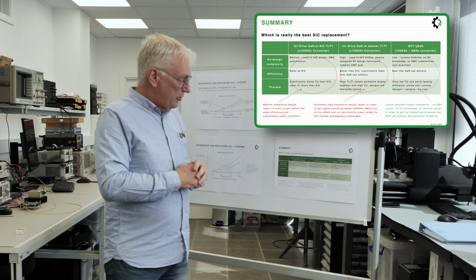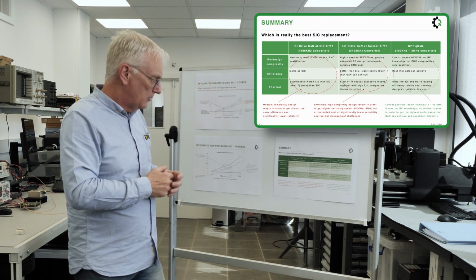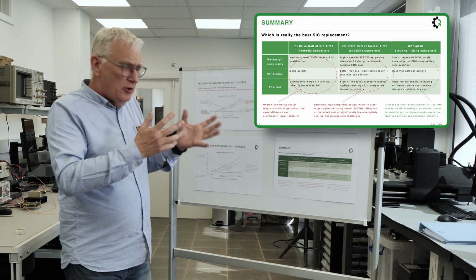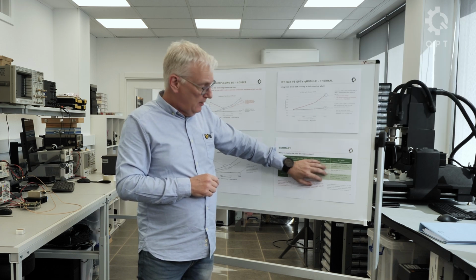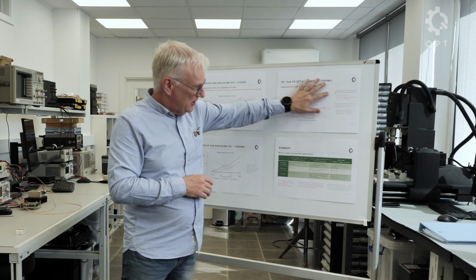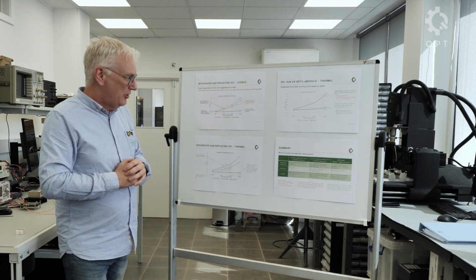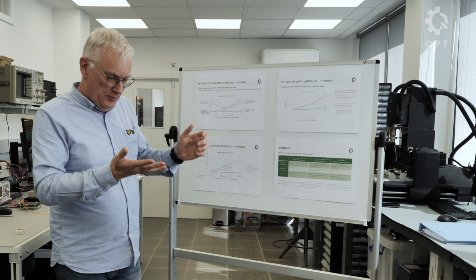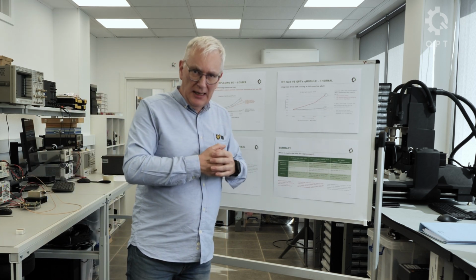So then the next option is, okay, you make it run really fast. Yes, you can do that. You save a bit of power. So you might have a more efficient design. But then because of the switching speed of the edges, you've got horrendous EMC problems. So this is an incredibly complex redesign for a relatively small amount of advantage, because you can see here it's still dissipating much more than we are. And then there's the third option, which is to use our QPT Q-GaN module, which gives you the best of both worlds. It gives you amazing thermal performance, it gives you no EMC issues, and essentially you can run up to 2 megahertz without any problem at all.